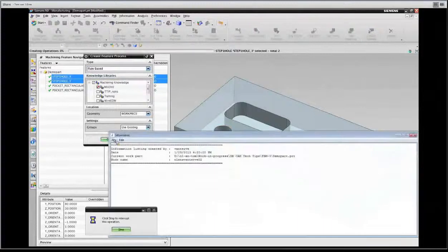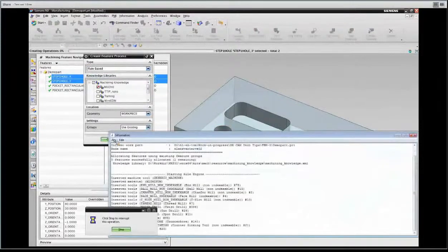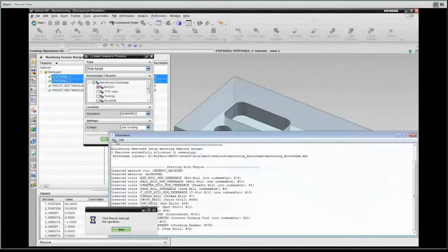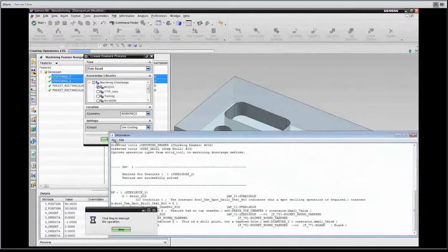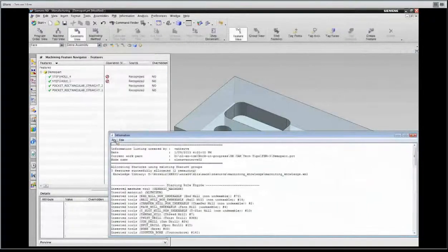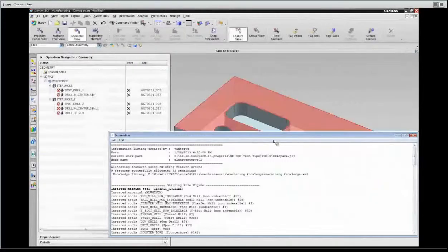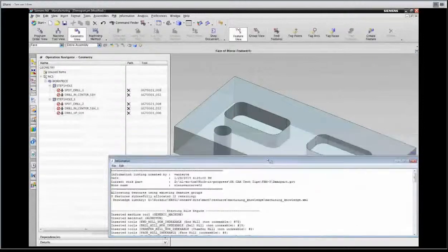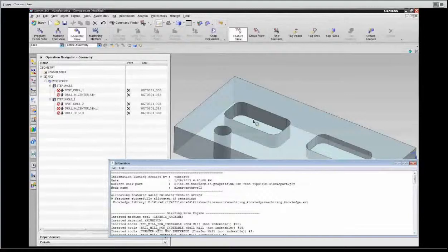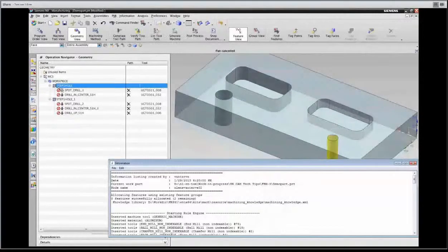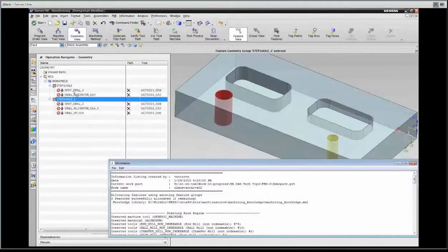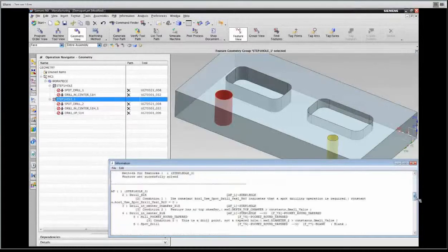It's back to a regular hole, and I'm just going to look at the out-of-the-box results, and I'm going to make some changes there, because you might be happy that you get a result, but you might be disappointed with the type of result because you work quite differently. So let's have a quick look. I did the 2 features, and if I make the window slightly smaller and move the part up a little bit, you'll see, as I mentioned before, both holes being spot drilled, and the larger hole being spot drilled and finally drilled a little bit bigger.